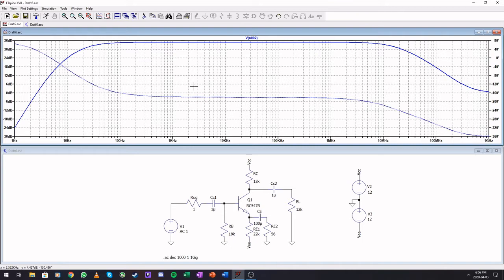But there is an output, but it's not exactly what you wanted. Quickly pop over to AC analysis and see the Bode plot. Sometimes the frequency that you are using as input is on one of the cutoffs, and you should just readjust for that. Okay, that is the AC analysis complete.